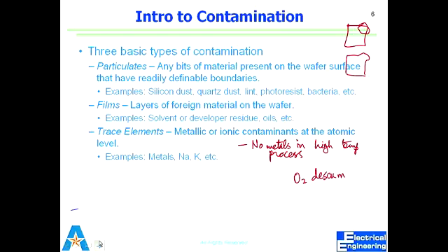So if I have a machine, say an oxidation furnace, right? It's a quartz tube. If I use a wafer that had metal on it and I heat it up to 1000 degrees centigrade, the whole furnace tube will get these ions incorporated. So now if the next person puts in his silicon wafer and does oxidation, those wafers are going to get these metallic ions incorporated. So do we want semiconductor material to have metallic ions? No, that's going to change the whole electrical property. So we call it contamination. For a layman, it's not a big deal, but for devices, it's a huge issue. Right?